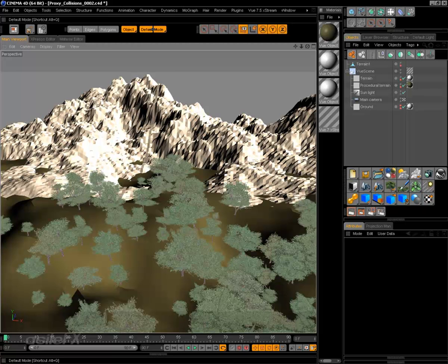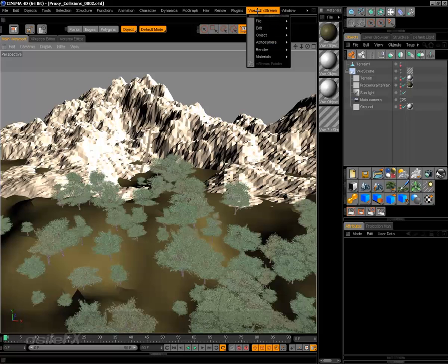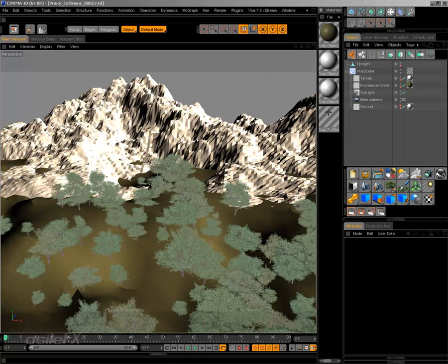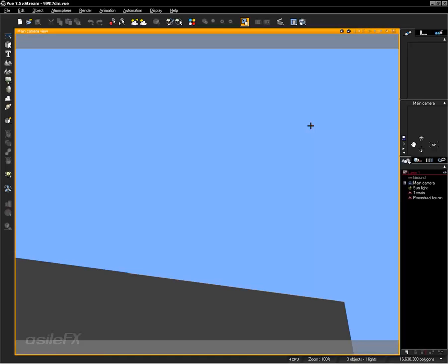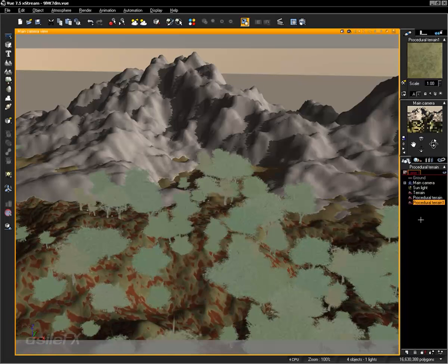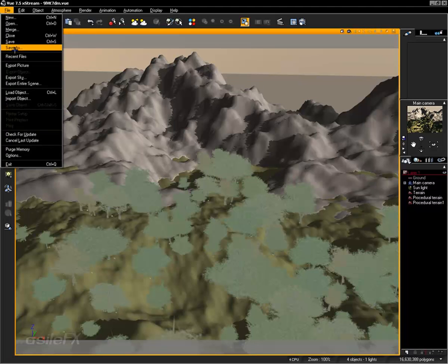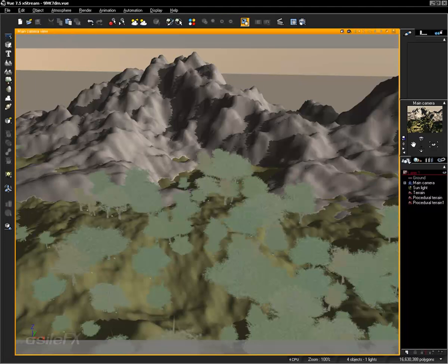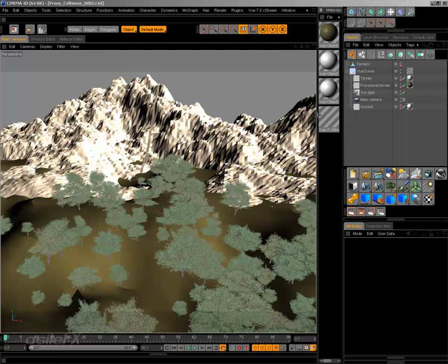So the way to get around this, I'm first going to just save the scene where it's at and open in standalone view. And we can just perform the action here. We're going to take our procedural terrain, copy and paste it, and now we have a duplicate. It's called Procedural Terrain 1. We can save the scene, close out standalone view, and reload scene from file.